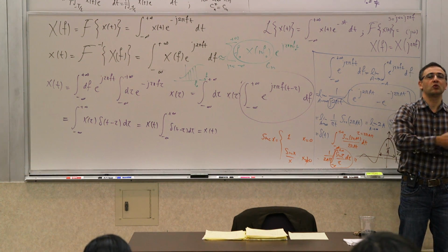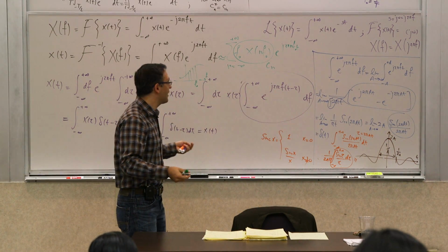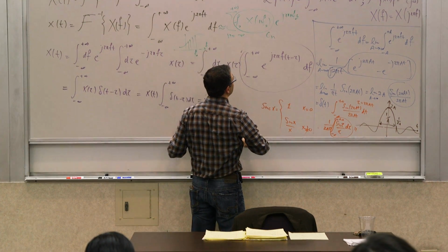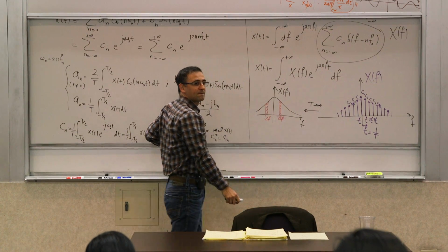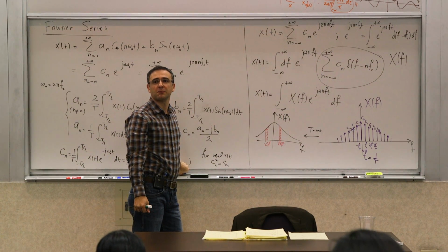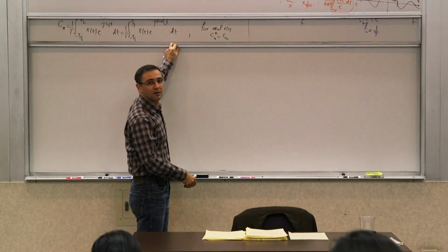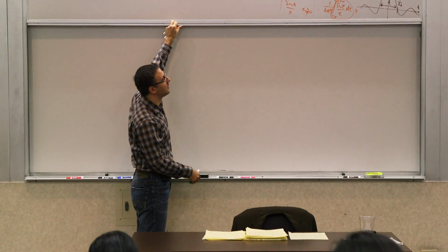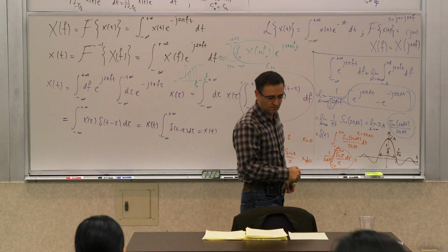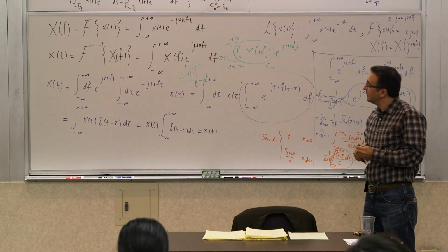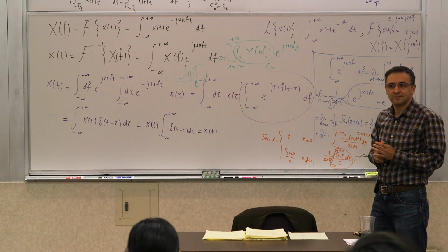in fact, right? So if you do a Fourier transform of a periodic waveform, what happens is that you will get a bunch of impulses. You will get exactly that. And if you do a Fourier transform of an aperiodic signal, then you will get a continuous thing like this. Does it make sense? Okay. Everyone's good? Shall we carry on?